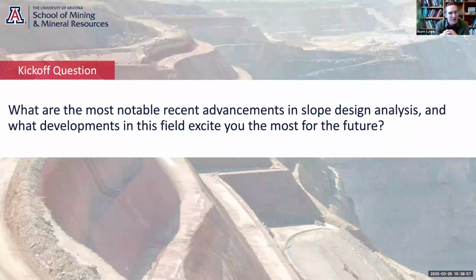And then for a numerical model, something that's happened in the last 15 years that wasn't possible before is now you can generate a DFN, which is a discrete fracture network. So basically all of the fractures, load that into the model, and then the model will just automatically mesh around those fractures, which is a really nice way to account for anisotropy or jointing in your model.